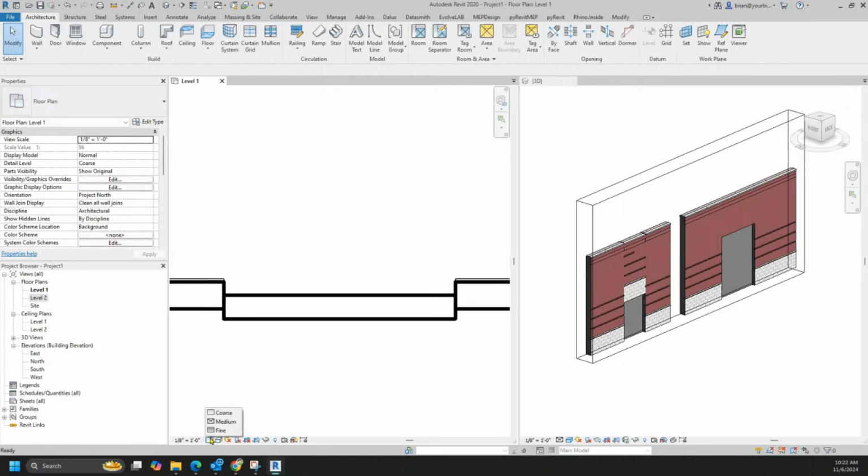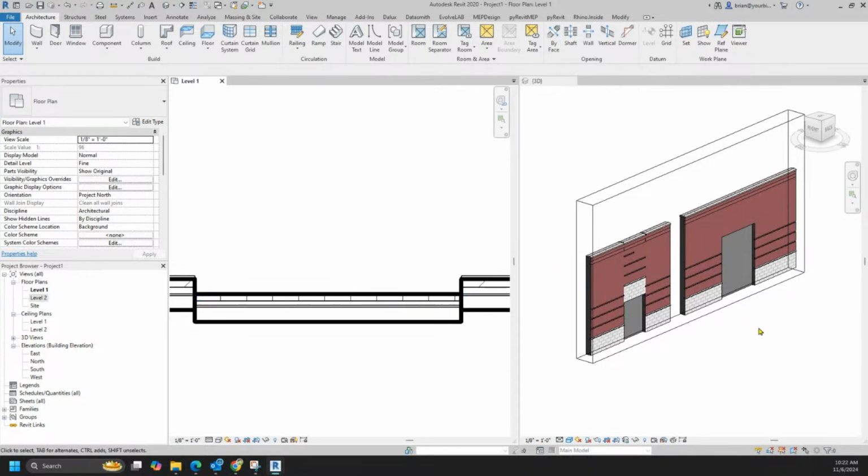And another thing that you would see is when you're looking at this in detailed mode, this doesn't make any sense because these studs stagger like that. What you really want is that stud to line up with itself, and all of this inset or outset, whatever you're doing to punch the wall, has to be done with these cavities in here. But this is a very common way that a model starts to get more developed.